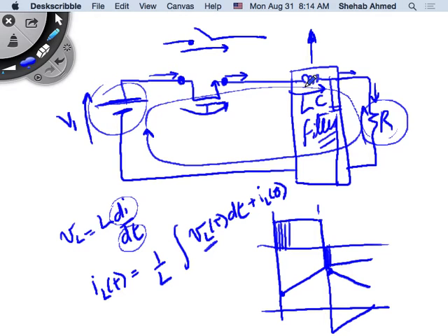This plus this equals 0. So this equals this, or this equals negative this. Doesn't really matter, right? As a magnitude. So the voltage across the switch is actually equal to the voltage across the inductor. Now when you try to open the switch, the voltage across the inductor goes shooting through the roof because you changed from a high value of I to a small value of I.